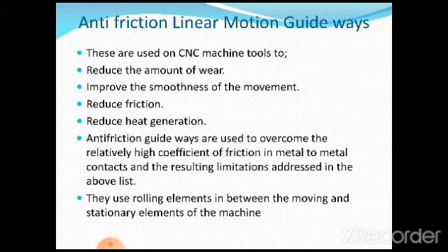Now we need to understand again in detail, okay, anti-friction LM guideways. What is the structure? You can have again what we have discussed. So you are going to see the rolling elements here. So these are called the rolling elements. As you are going to see, the rolling elements, whatever the direction, also you are going to see very clearly how the movement is going to take place there, and how the carriage is also made to move. So the friction force between the rolling elements and the carriage is there, and that is very small.